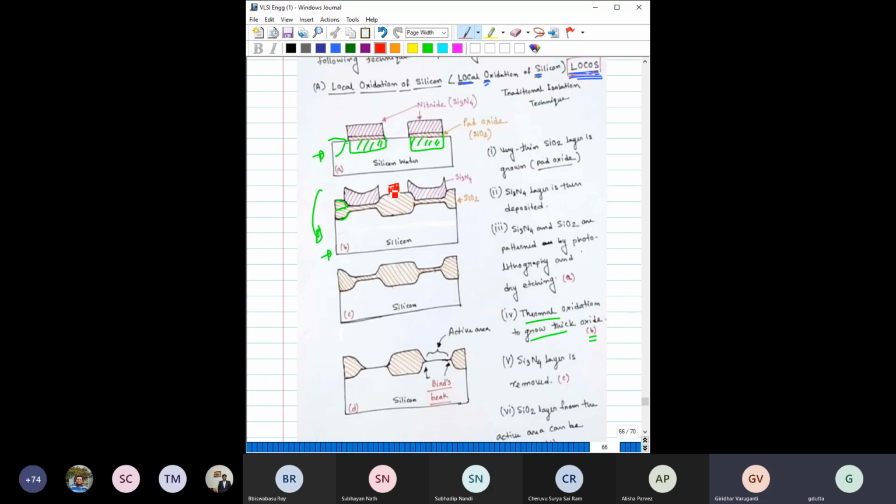Because you have to route the contact line on the wafer surface. If you route it on a thin oxide, then easily below that a channel can be produced, because you have some potential on this line, and that may create some issue. But as it is a thicker oxide, its threshold voltage is very high, so probably at this voltage no channel will be created. So that is one advantage of using this thicker oxide.